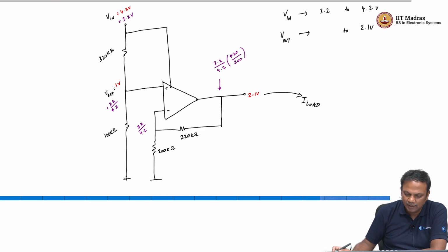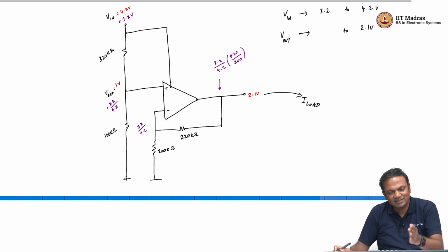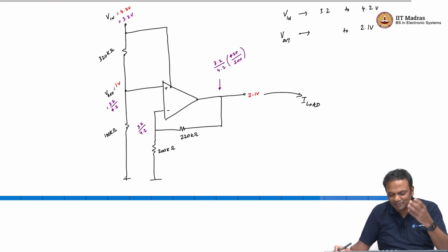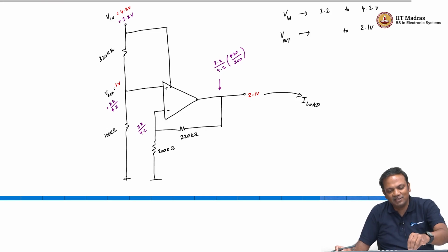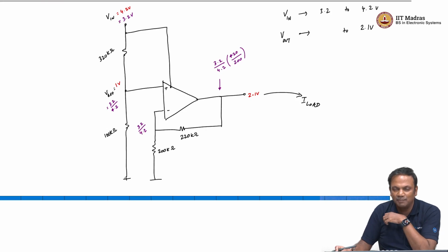correct. I mean, it is no different from the previous calculation, you would have probably realized that by now, but it is just essentially saying that V in went through one resistive division, then it went through 1 plus R2 by R1 amplifier. So, resistive division and then one multiplication.